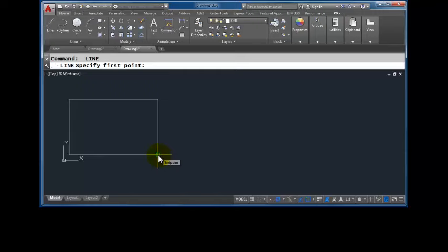These views are 2 inches apart. If I hover over the endpoint on the right-hand side of my front view and start to track, I'll enter that distance, and I'll start the next line exactly 2 inches from the front view. The bottom edge of this right side view is 2.25 inches long. Swing my cursor up. I can either direct distance entry this length, or I can hover over that endpoint on the front view. Remember, these are the same object, just different views, so these should match.